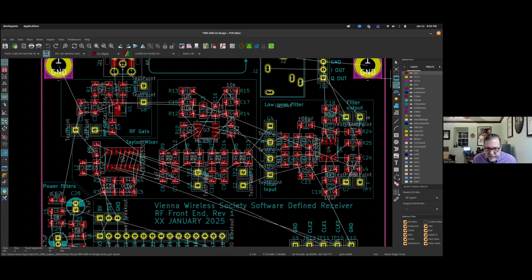You've already decided that this layer is going to be your RF layer, and then the other side is going to be your digital side. It's going to be a bit of a mix. I will have some digital on this layer. I might have some digital on the other. There are many different philosophies for approaching what you route first and in what order. I like to route the most sensitive traces first, the ones that are the most intolerant of imperfection.